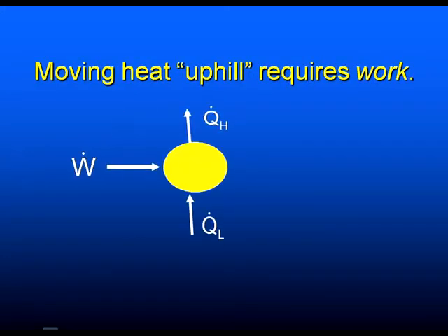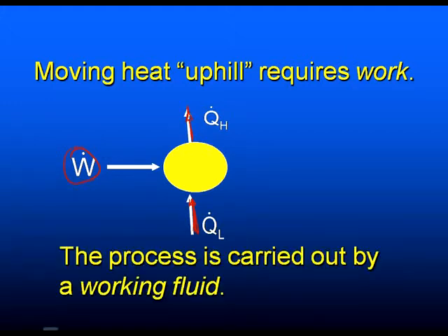That requires work, so we're going to have to put work in to make the heat go against its natural inclination to flow downhill in temperature, or make it move uphill in temperature. And to do this we use a working fluid. The working fluid stores the heat and moves it from one place to the other.